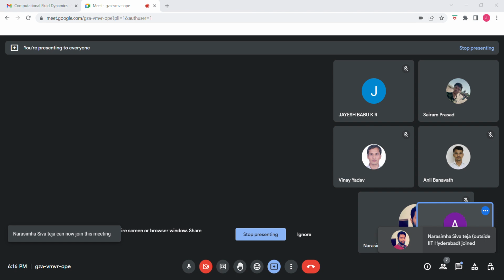In order to get that, we convert the partial differential equations into algebraic equations by discretizing them, so we have that many equations. To solve those equations, we need some iterative techniques, so we use the Gauss-Seidel method there. So the first option is that matrix A is non-singular.